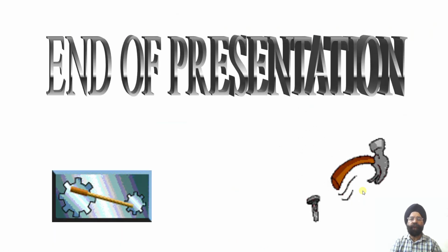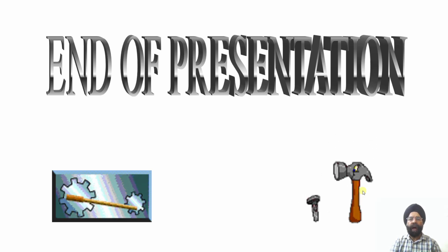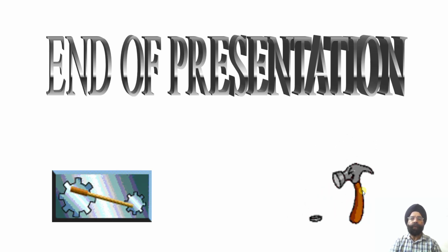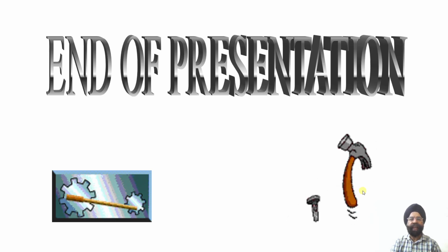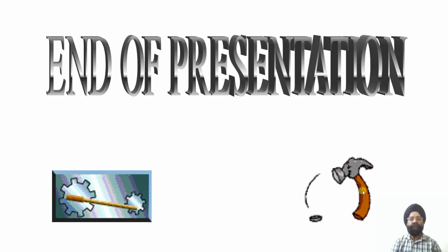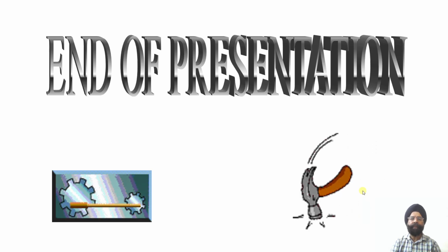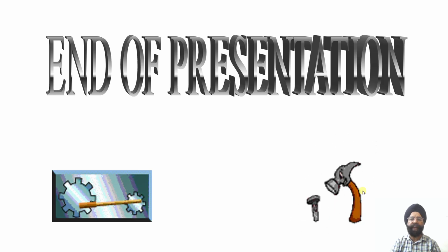So this is all for today. I hope that through this discussion you would have understood how you can go about conversion of a real world situation into the projections of the oblique line using the principles of orthographic projections, and thereafter how we can use the principles of rotation of the line method in order to evaluate the true length of the line as well as the true inclinations of the line with respect to the two reference planes HP and VP.